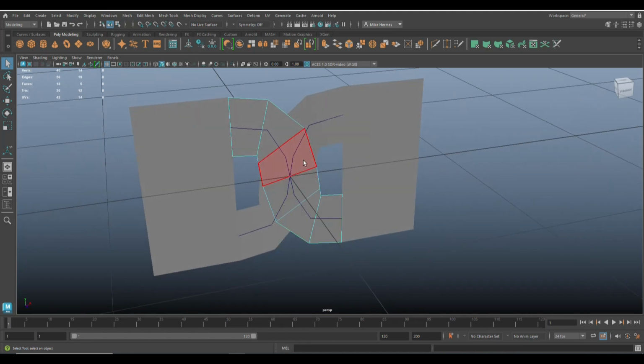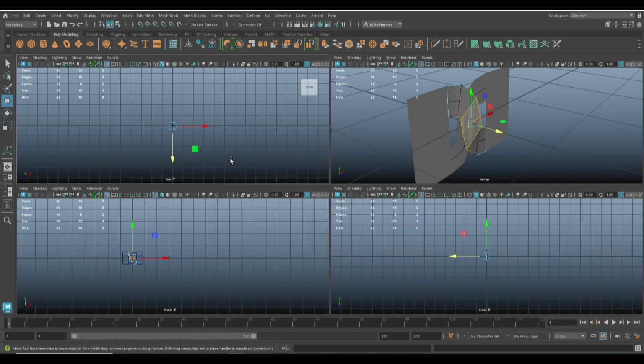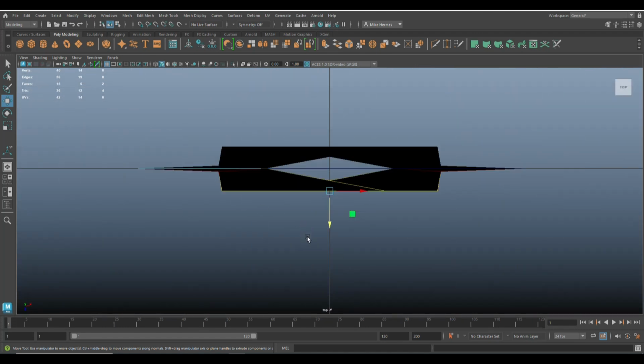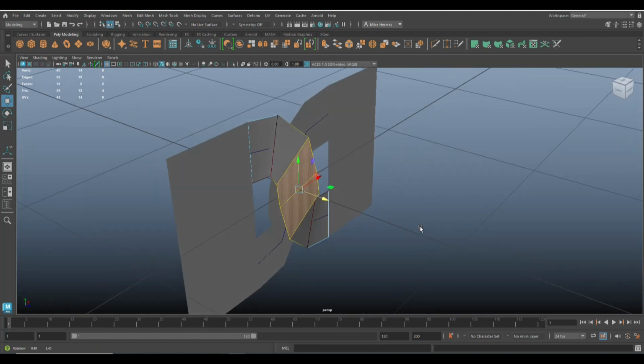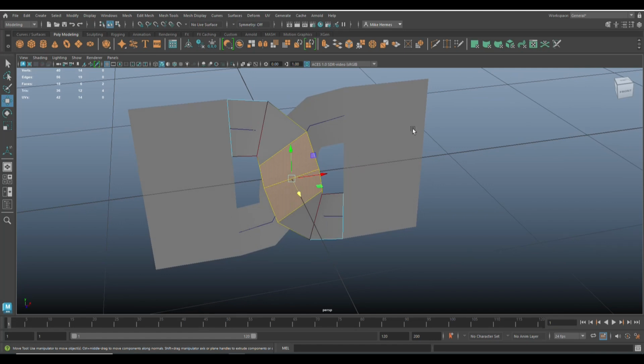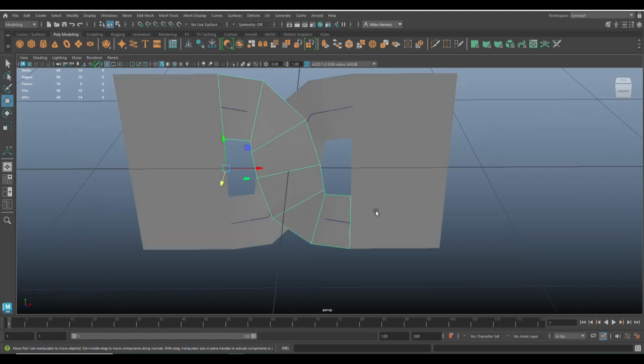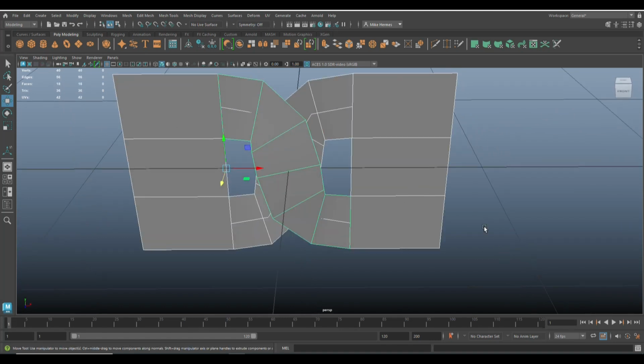So right click, go to face, 1 and 2, hit B for soft select, which is still in the same range. Hit W, move that, and let's jump to the top and see if that's about the same distance. It looks like it is. Yeah, good. And now we have to put Humpty Dumpty back together again, right? So what we're going to do is make sure that we didn't move anything here. We did not. Drag select the whole thing.